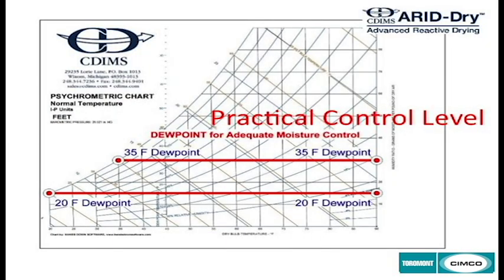And what it says is that they need to control their facility to 60 to 65 degrees F and no higher than 40% relative humidity. And they need to achieve that condition within 3 hours prior to the game and hold it throughout the entire game. That's what the NHL requires of these facilities. And the only way they can do that is to actively dehumidify the facility.